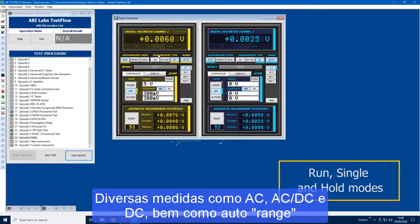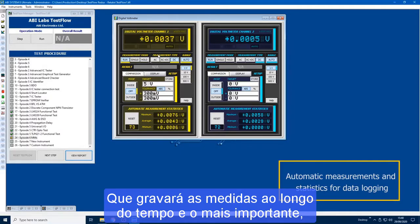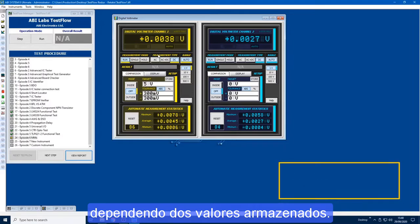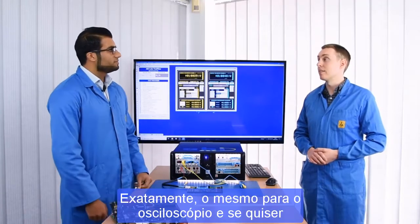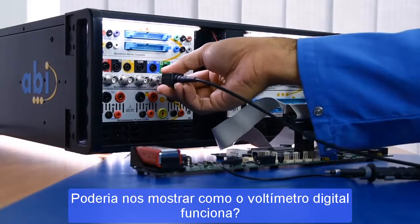Okay, different measurement types, AC, AC-DC and DC, as well as auto range, or you can select a range of your choice. It also has automatic measurement statistics that records measurements along your recording, and most importantly, our comparison, which gives you a pass or fail depending on if it matches the stored value. That's great, and this works hand in hand with the test flow, so you need to set this up once, and then once you've probed your test points, you either get a pass or a fail. Exactly, same for the oscilloscope, and if you want any more of that information, you can find the link in the description below. Can you show us how the digital voltmeter works?